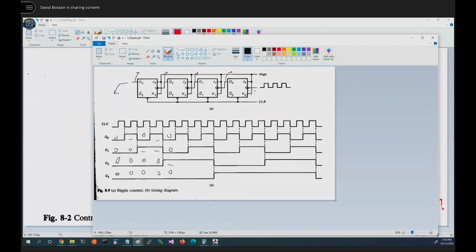And the idea is that once we've seen the clock, propagation delay later, we give him a clock. Propagation delay later, we give him a clock. Propagation delay later, he gets a clock. Propagation delay later, he's stable. So in spite of that, if we were able to look at the values at a fairly slow, reliable pace, maybe on the rising edge of this clock, they'd be stable by that point. We'd be able to see a binary count.